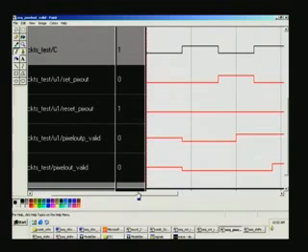And the user can process further when this is asserted, and he can take the actual pixel value, and if he has a storage elsewhere, he can store it at the positive edge of the clock subsequent to the rise of this. So it therefore indicates the validity of the pixel.